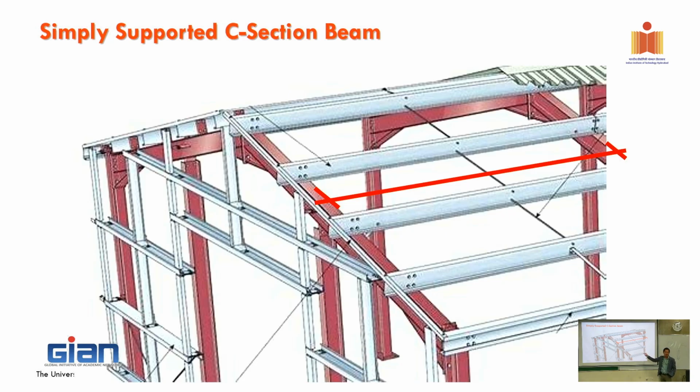The purpose of that rod, right? So what is that? About the minor axis. Exactly. So when you talk about minor axis buckling, so what is that stopping? It should be at the compression flange. Yeah. So the role of this one is to stop the purlin or the channel section here from flexural torsional buckling, or in the US you call it lateral buckling. So a similar term, but in Australia we call it flexural torsional buckling.